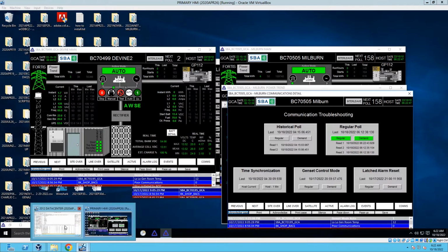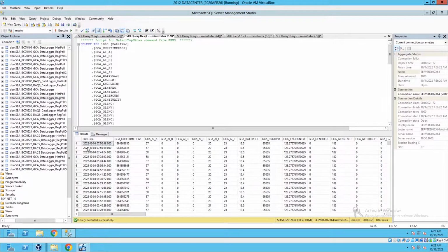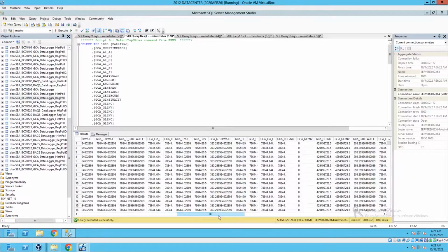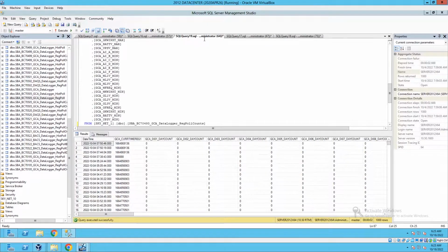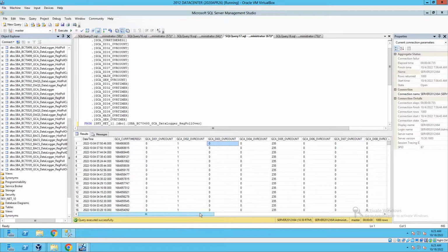Every value we read back to the host is stored in the SQL tables, providing granular, powerful raw data sets that can be organized to meet future demands. This includes min and max values as well as counts and timers on digital inputs. Even our historical polls are stored in a similar fashion to ensure quality granular data is stored for detailed review at a later time. There is no decay in granularity as there is with many systems in industrial operation today, which allows year-over-year comparisons to be conducted to assess efficiency of machines and other technical attributes.